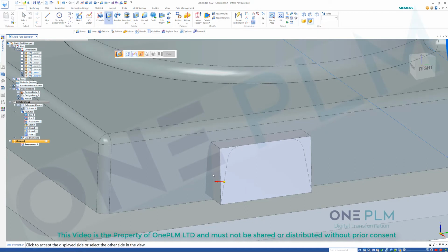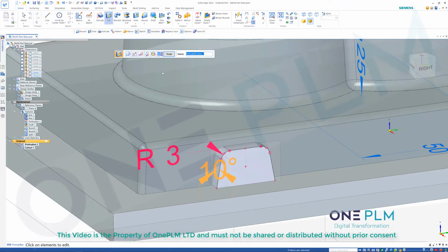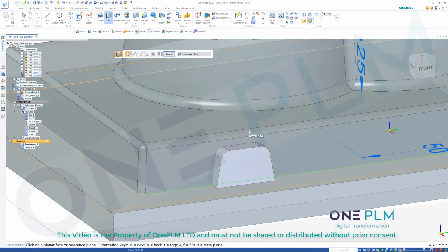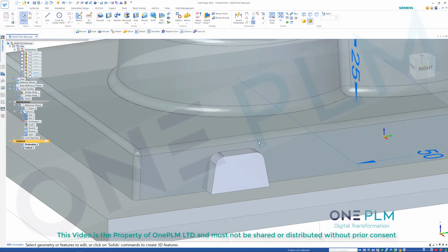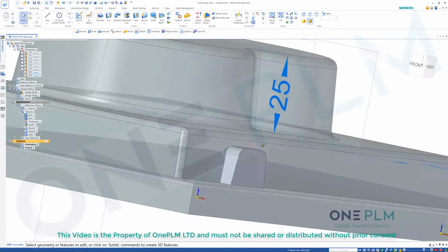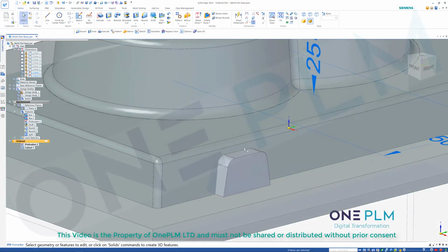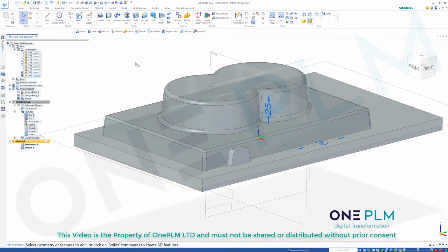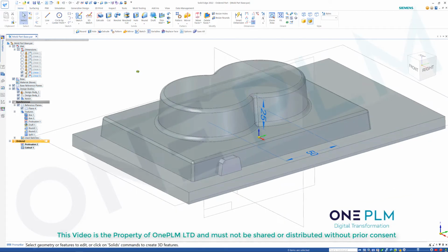This is a cut open profile, so I want to make sure we cut on the outside. I've got that set to through all anyway, so that's going to cut all the way through on there. We've got these settings for selection step, that's doing the active body, which is that notch body, which you can see is blue. Otherwise we could have done selected body as well. There's two options that we've got on there. So if we close out of there, that's looking okay. So just going to save that, do a quick Control S on there.